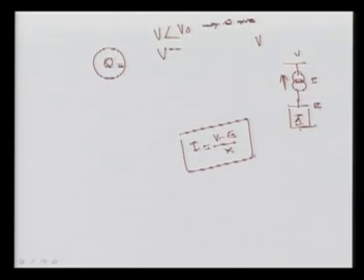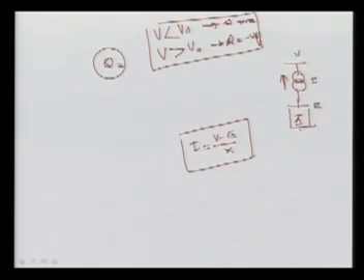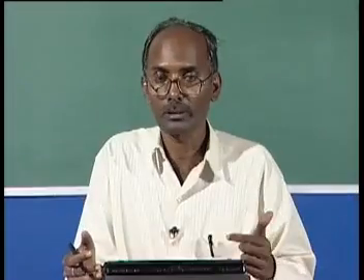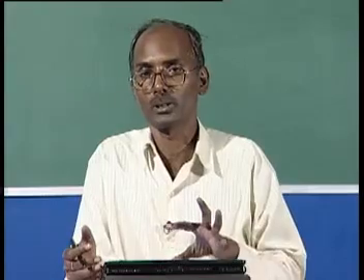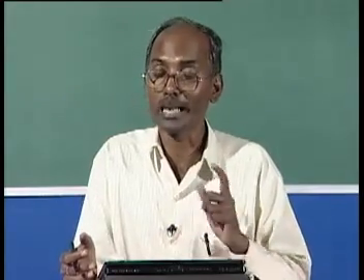When V is greater than V naught, they will absorb reactive power, and normally they will get it from the system to maintain the voltage. So these devices in the steady state will work like simple reactive power support devices, but their supplementary controllers can be used to improve the dynamic performance.